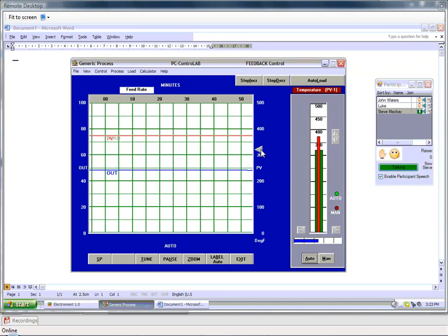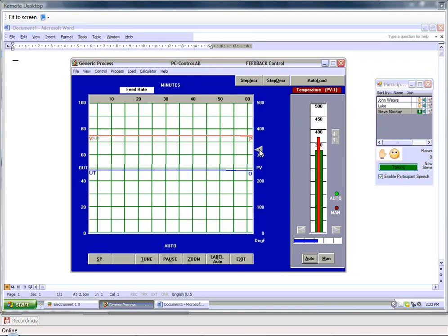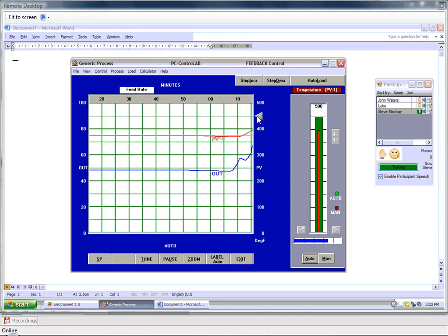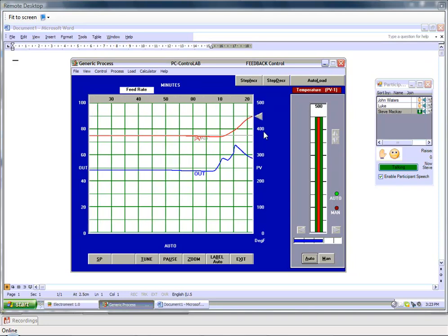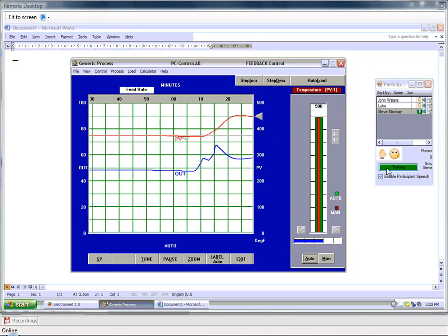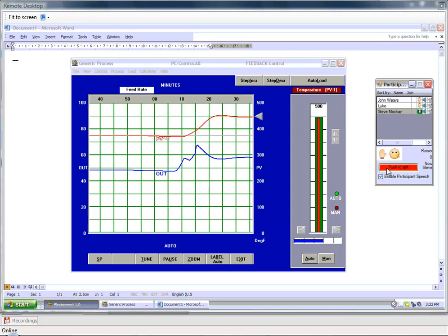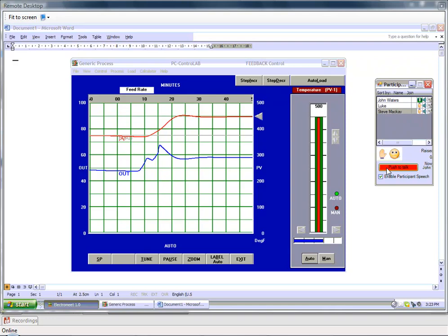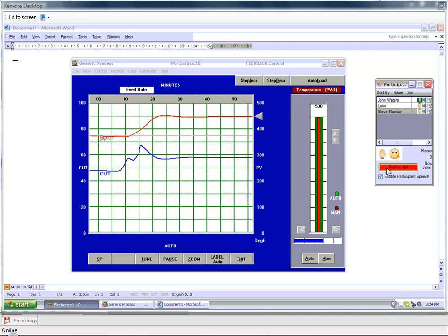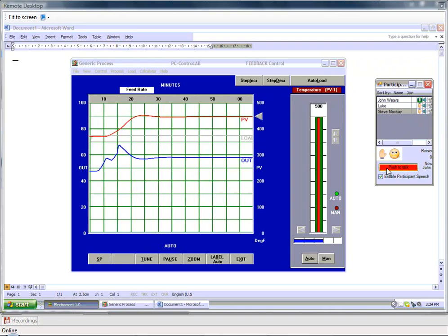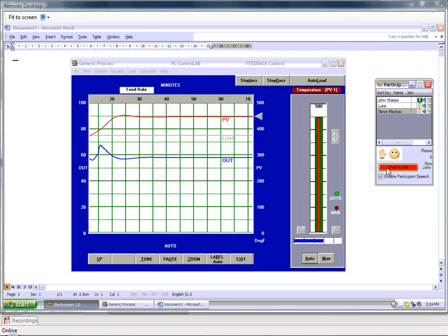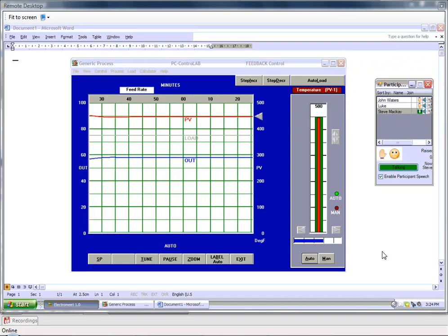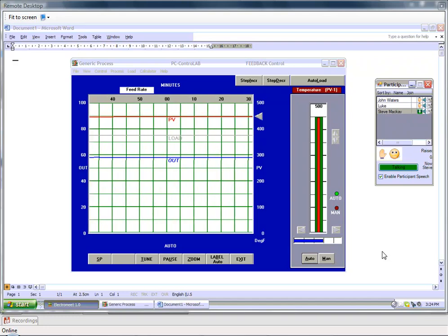I will switch it into automatic mode now and generate a change in the load. You should be able to see both the output and process variable begin to change, as has happened here. So now on the right screen you can see the process variable settle about the intended level of the actual load itself. So after generating these responses, we can show that this enables us to basically demonstrate a local